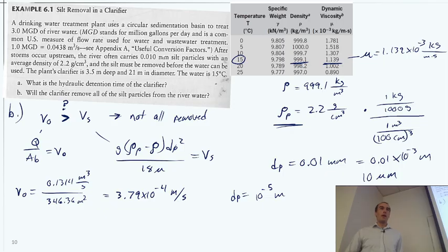That's a good way to double check your calculations: is this going to be heavier, or more dense, than water for a sedimentation problem? It shouldn't be 220. That's much lighter, it's never going to settle, it's going to float. Is it 2 million times the density of water? That's probably wrong also.